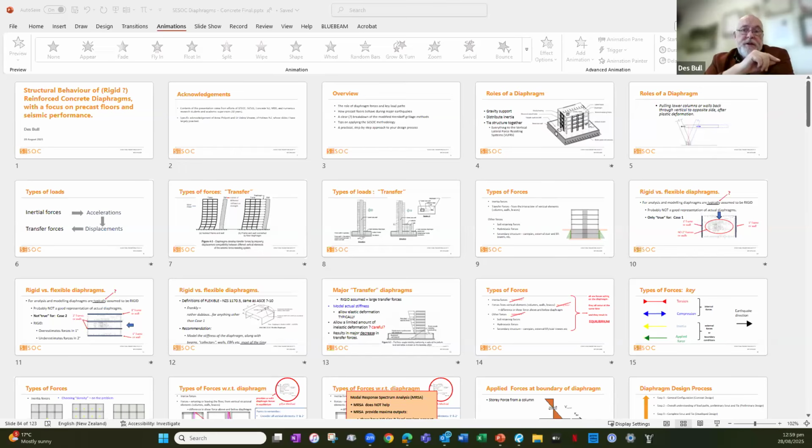If I've understood the question, and I may have misunderstood the earlier question, when you do your computer model, your 3D model of your whole system, using the ACI or ASCE section modifiers for diaphragms is a really good place to start. For your diaphragms, you're not using I gross, A gross for your diaphragm model in ETABS.